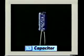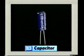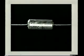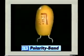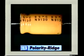Polarized capacitors, whether axial or radial, will have either the positive or negative lead marked. The positive lead can be marked or formed in several ways, with a symbol like a plus, dot, or band. The positive end can also be marked by a colored end or a silver square, or by a ridge or bubble.